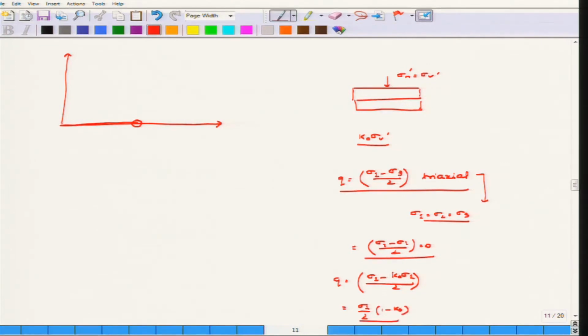So, obviously the line would move somewhere in this direction, because now it has the ratio of sigma 1 dash, and then along the shear it moves along this direction. So, this is for our consolidation line, and this is for a shear. These are the two definitions that you have to remember, that is how the stress path is going to behave in case of a direct shear. If it is directly a shearing line, then obviously it should go directly from the point 0 0, but if you allow a consolidated drained test, for example the CD test in case of a direct shear, then obviously there is a consolidation line, and from that point of the stress, let us consider from this point, it will move along the shear line.